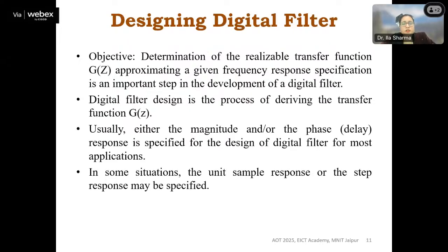So the objective of this digital filter is to determine the realizable transfer function. Again, it should be stable, it should be linear, it should be accurate, it should have low pass band error, low stop band error, right? It should not have any delay. So these are our requirements.